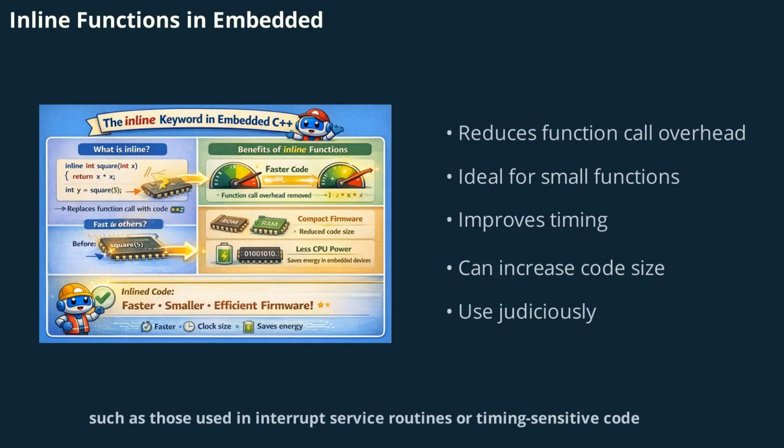routines or timing-sensitive code. However, it's important to use inline functions judiciously, as excessive inlining can increase code size, which is a concern in memory-constrained embedded systems. Balancing performance and code size is key when deciding to use inline functions.